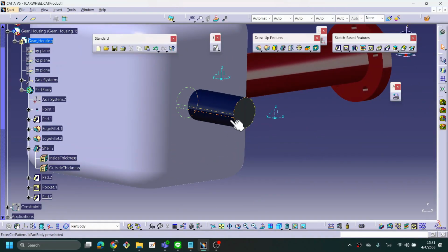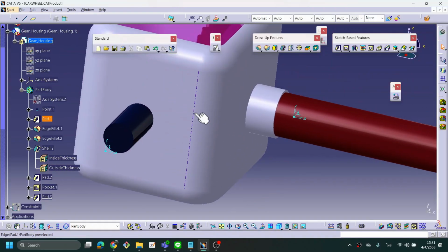You see the technique when you use the product and create a solid in the part. One by one, use the product structure tools to create a new part in the product. Each product is composed of more than one part. I call each part a component.